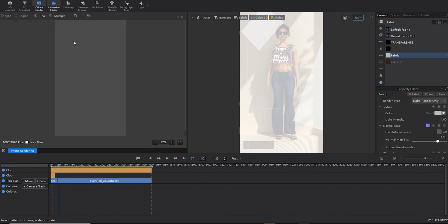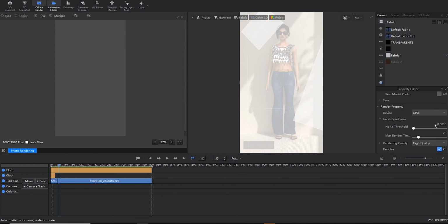All right, so before you render it, it is important, whatever render tool you're going to use, because now we have the ray tracing tool that is a super fast render. You need to configure your output, your image sizes. So you just click right here. If it's an animation, you edit the proportions right on this button, and you can adjust resolution, which sets the proportions of the image. So if it is for reels, for example, for Instagram reels, you could just use these proportions.